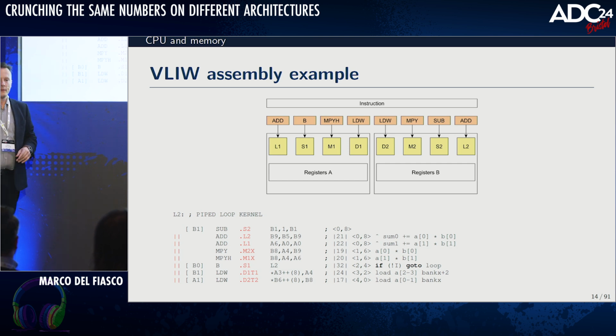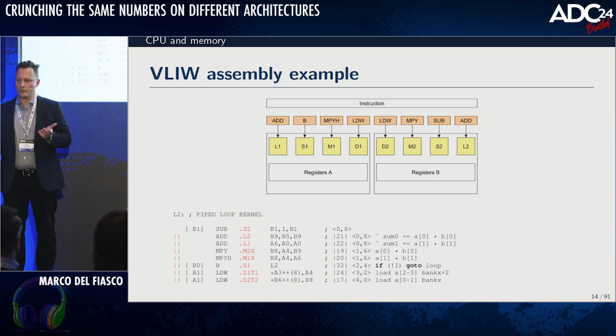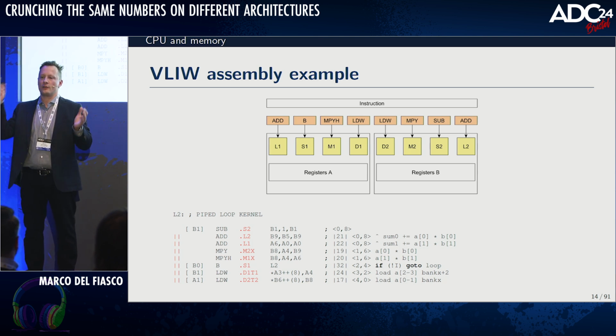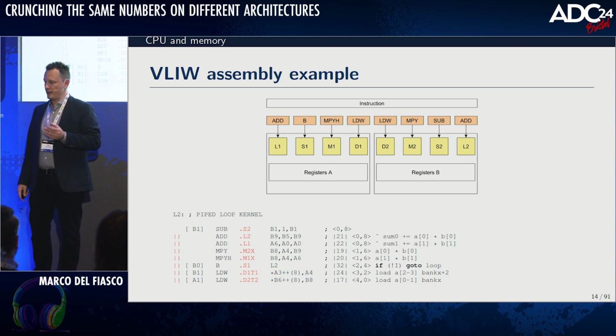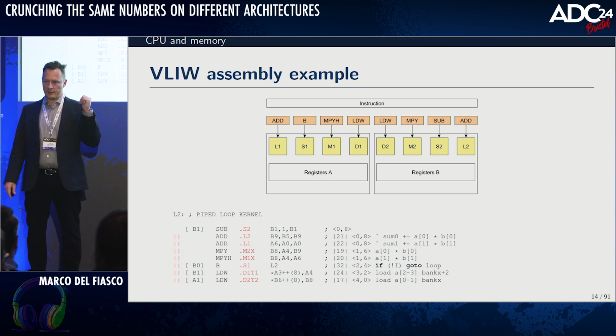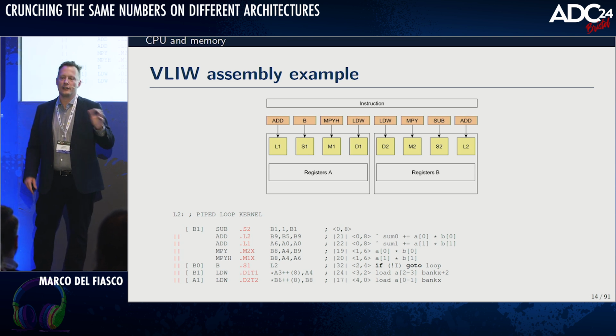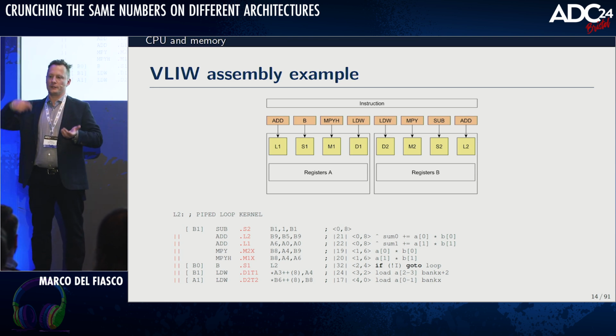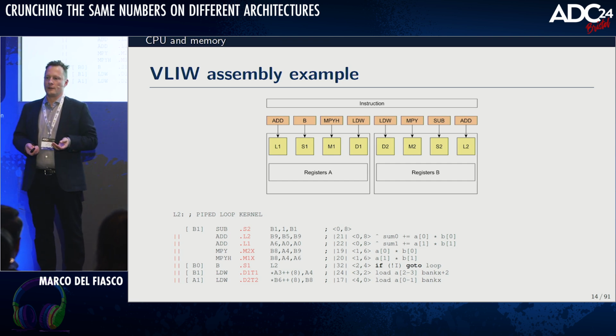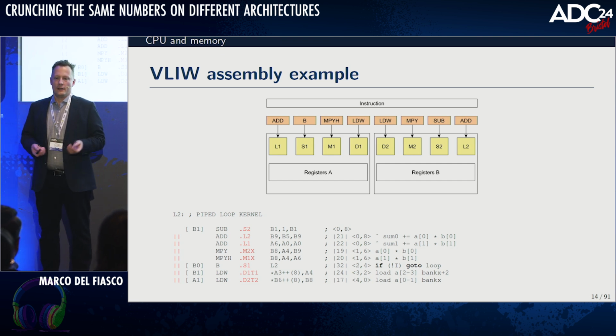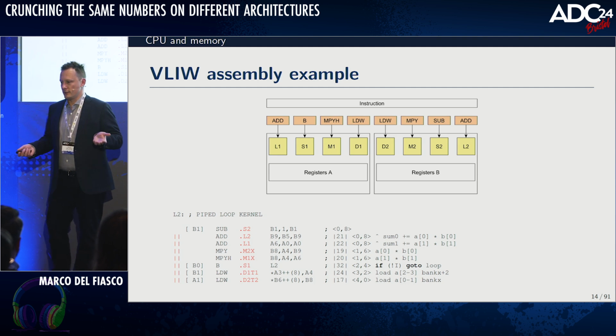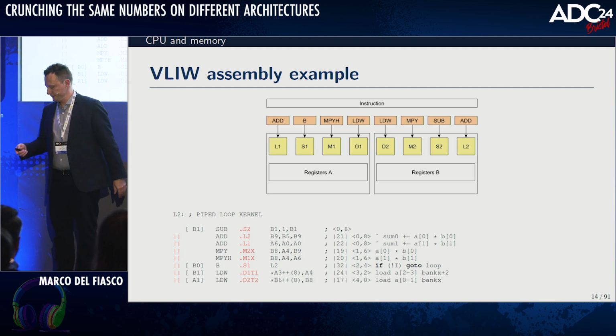And the programmer needs to know the architecture of the machine because they need to know how many cycles each instruction requires. So it's very, very hard to write like this. Typically, you will use linear assembly, and you will run an optimizer after the assembly code. But nowadays, implementing straight in C is the most common and viable choice.